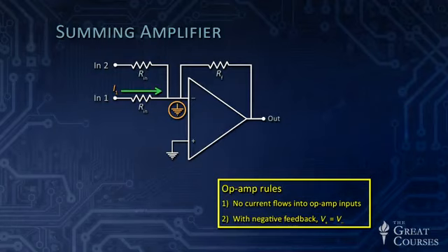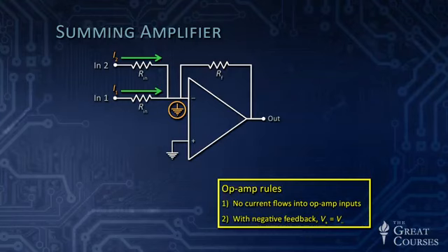Because what happens at that point is currents that are coming in through those 2 resistors all think that they're going right to ground. So they don't know anything about the other currents that are flowing in the other resistors, and they become completely independent of each other.